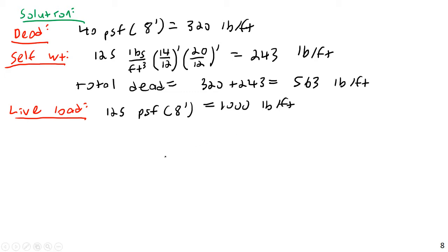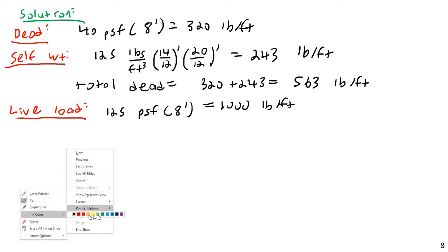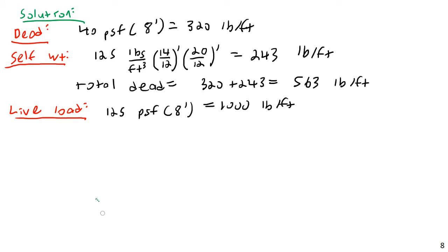And then I want to look at the factored loads. So I have my individual loads, factored loads, etc. Now, we could look at the 1.4 dead, etc., but in this particular case, I can very clearly say that the 1.2 dead plus 1.6 live will control, because the live load is so much greater than the dead load. So then I want to get the factored load.